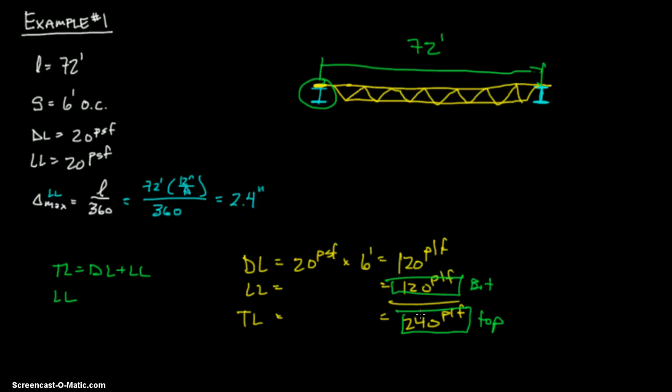Now it depends which one you use. I would use the 36 compared to the 40 because it's lower, and usually you'll mess with height issues, so you'll want the thinner roof, but sometimes it won't matter, so you go with whichever one is cheaper. In this case, the approximate weight is about the same, so you would assume that the 36 would be slightly lighter. So I would go ahead and use the 36.